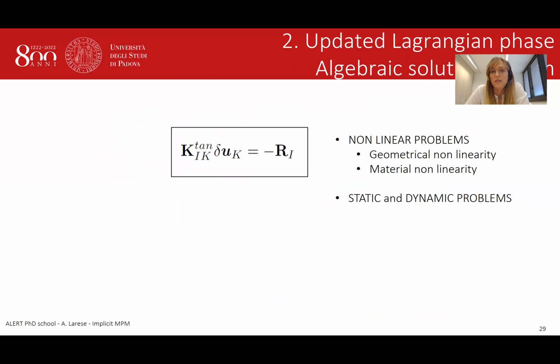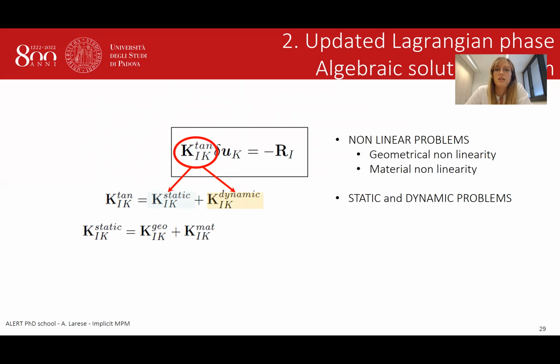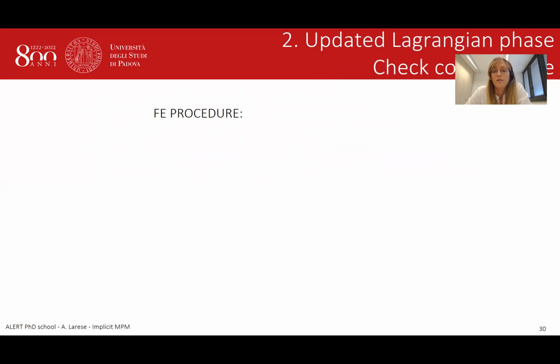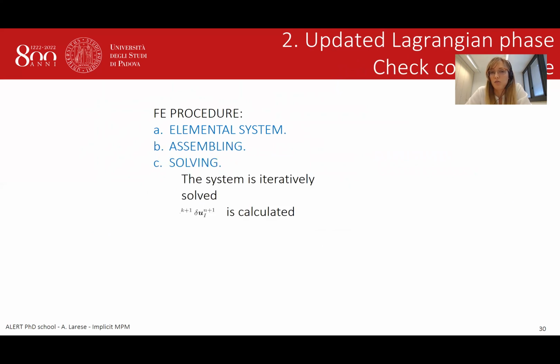What we are solving is a system of equations of the classical type, so stiffness matrix, unknown, and residual of the momentum equation, of the governing equation, basically. Since it's a nonlinear problem, we will see it when we speak about formulation, but we need to linearize our nonlinear problems using Newton-Raphson schemes, basically. I'm not entering the detail of how this is built since, as I said before, we will analyze the formulation very briefly.